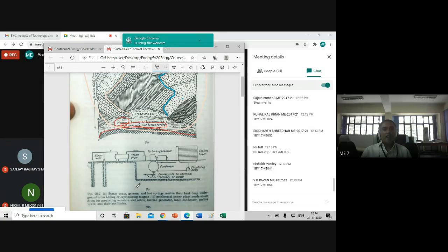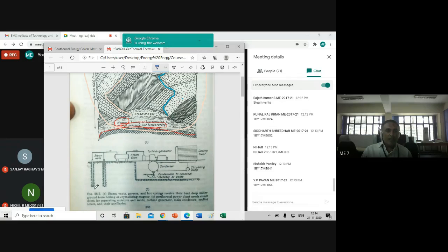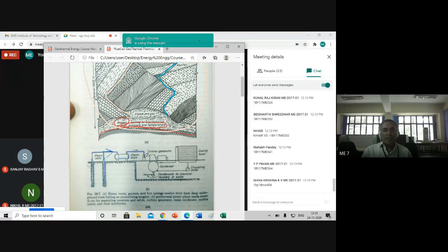Okay, this is one hydrothermal geothermal plant they are showing here, the diagram which is shown below. Here, this is the steam well. They will drill it, and they will take the steam. That steam flows like this. Then that is taken to the steam drum, and here separation of the particles, moisture separation, takes place. That flows to another valve, then it goes to the turbine.